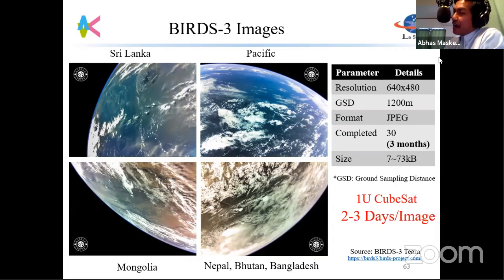If they have not used it, it's probably better to test. But if it's a pico satellite or a nano satellite that's only up for 1 or 2 years, you can make an argument, if somebody says do a radiation test, that maybe it's not necessary. But in that case, I would still recommend it, because it's a new module.